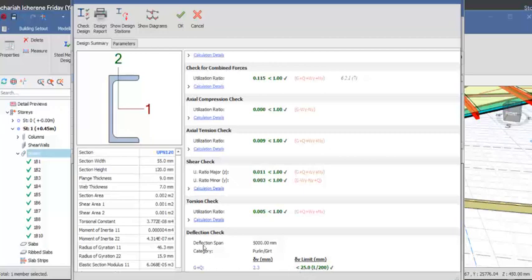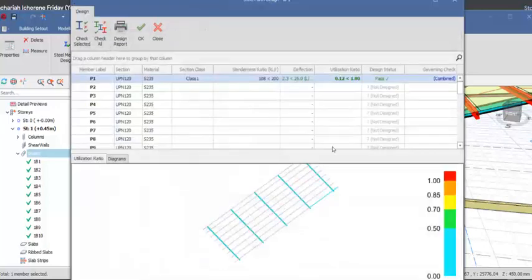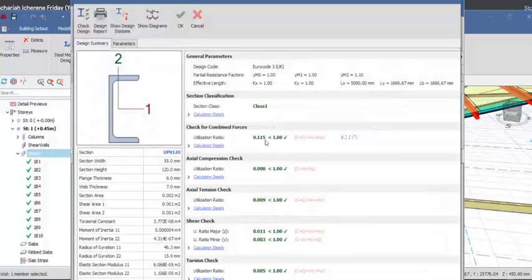So you can see the deflection check is okay right here. Click on the OK option, and then if the U ratio is very much smaller, you can reduce the sections. So you see the U ratio at 0.01. So it's smaller. You can now go ahead and change the sections of the lines, so it will be cost effective. Alright.